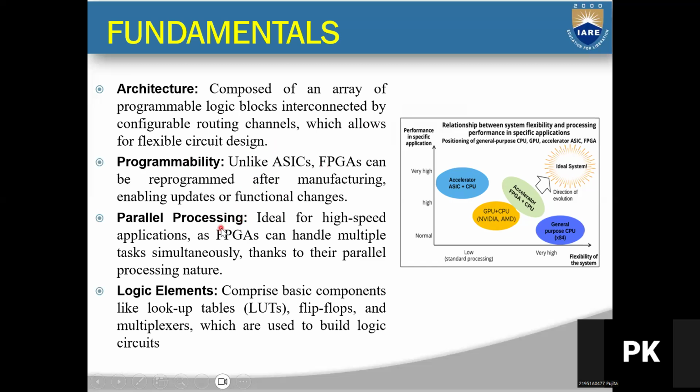So, what is parallel processing? This is the main fundamental used in FPGA, ideal for high-speed applications, as FPGA can handle multiple tasks because of this parallel processing. Logic comprises basic components like lookup tables, flip-flops, and multiplexers. So these are the basic fundamentals.